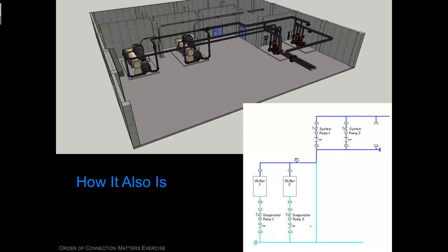Now, I said, for the purposes of our exercise, we were going to assume that the loads on the system were across the mains and two-way valves. So let's go ahead and get our load drawn on here. And then we'll talk about how a variable flow primary-secondary system like this works. So there is an air handling unit. That'll be like typical of many, we'll say. And pipe comes out of it, put a two-way valve on it. And there's probably service valves and stuff that I'm not bothering to draw right now in the interest of just getting to the explanation of how this works.